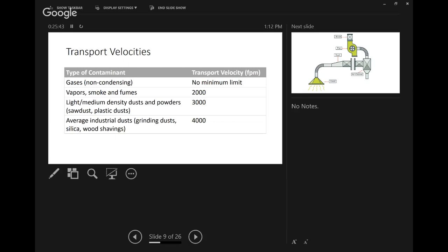I don't know where it condenses, where it goes from gas to liquid, but it would have to be so cold that the gas probably isn't your biggest concern. So for some gases, to go from a gas to a liquid or liquid to frozen, the temperatures are so low it's just not realistic that you'll ever see it. So carbon monoxide is a good example. It's not going to happen. So you could have really low flow rates here and you're going to be fine if that's all you're trying to transport.